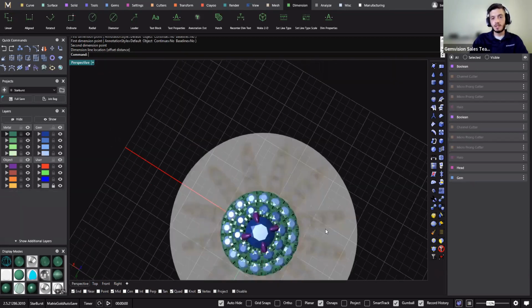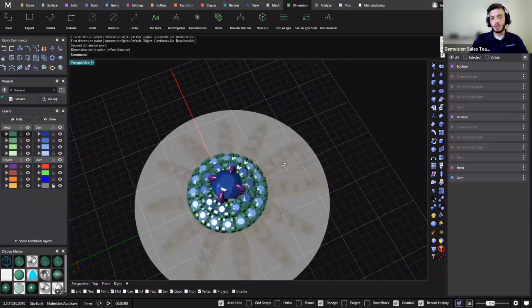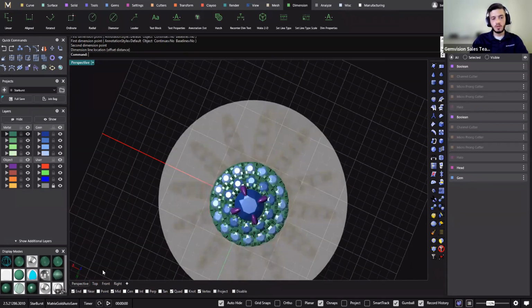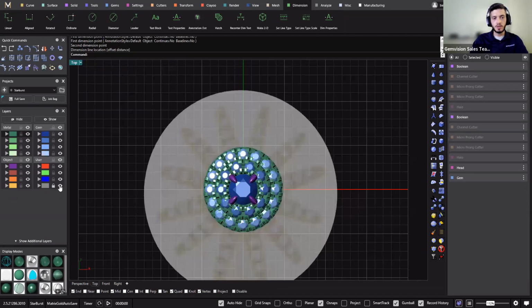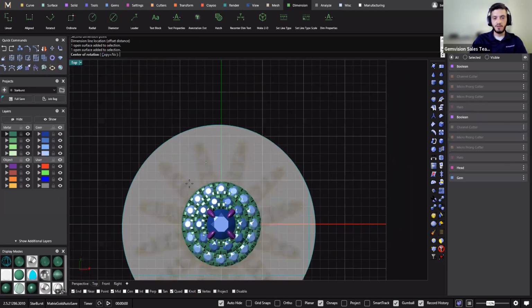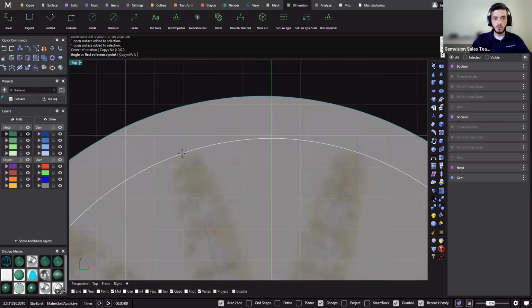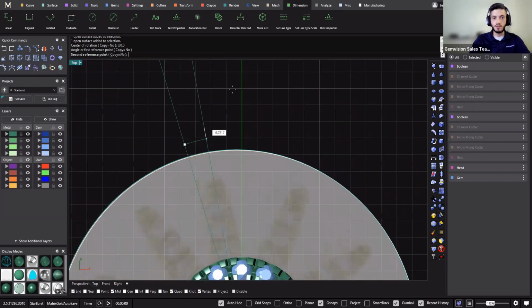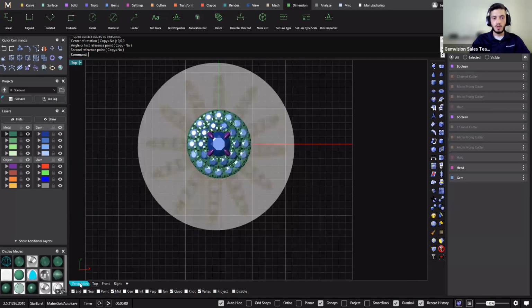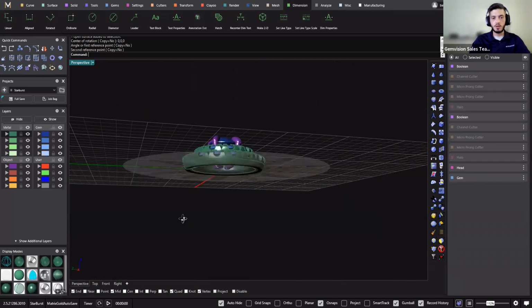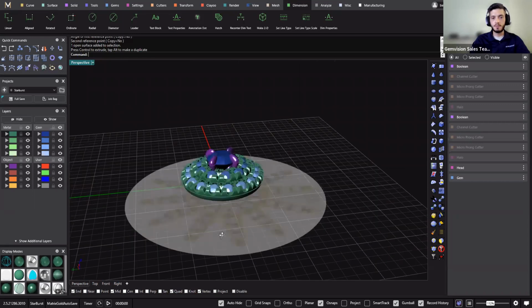All right, so the last thing we need to do is create these little starbursts. What I want to do is unlock this, and I want to rotate one to be straight north. That way I can get accurate dimensions. So to do this, I want to rotate from F4 and just go straight up like this. Take him and hold shift and enter. Can pull them down just a bit. That way we have room.